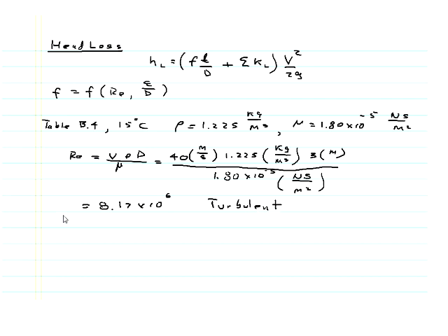It's also stated that these are smooth pipes, which means that the relative roughness epsilon over d is 0. So we'll use the Moody chart, which is the plot of friction factor versus Reynolds number.